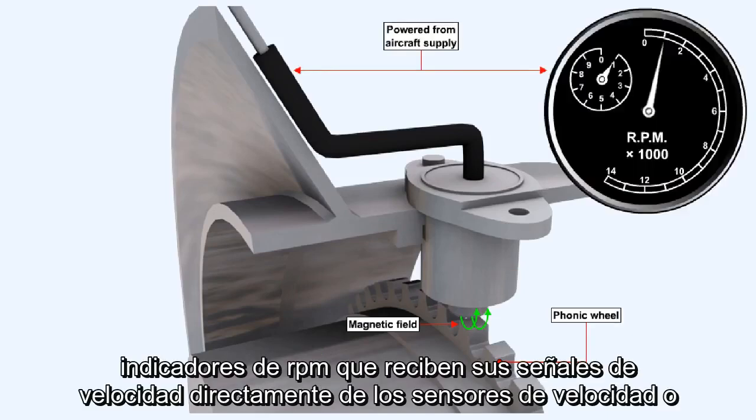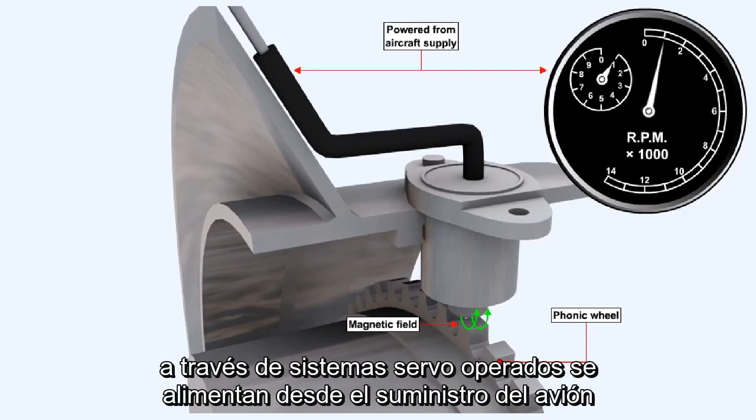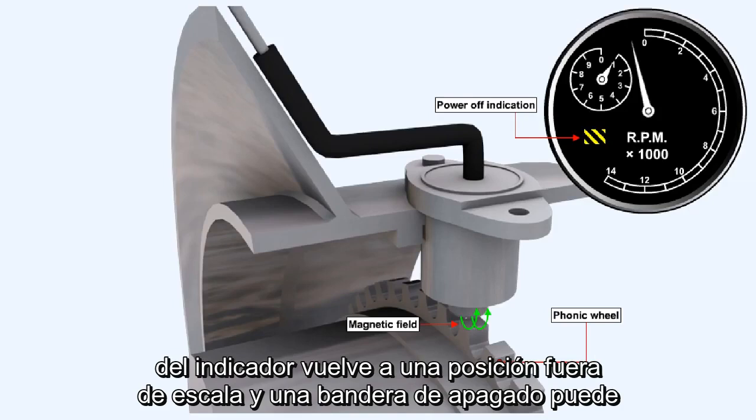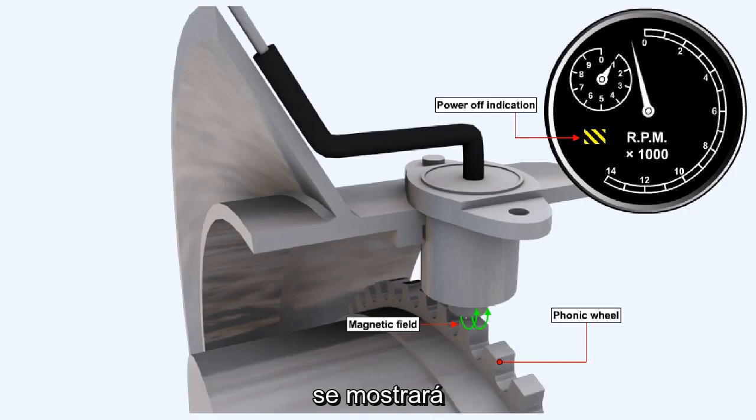RPM indicators which receive their speed signals directly from speed sensors, or via servo-operated systems, are powered from the aircraft supply. In the event of either a power supply failure or a signal failure, the needle of the indicator is returned to an off-scale position, and a power-off flag may be displayed.